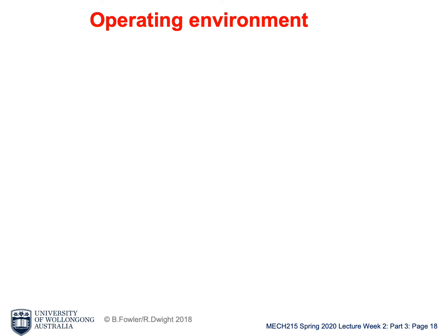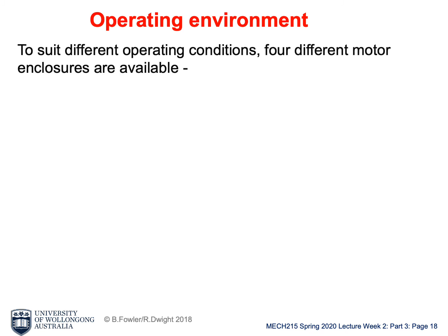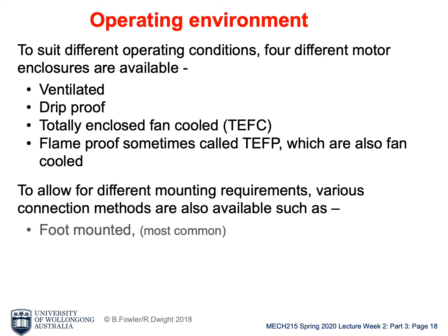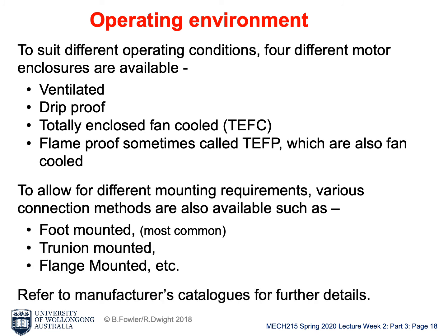In real applications, the operational environment factor is also very, very important. There's a lot of information. If you open any motor catalog, there's a lot of information about how the motor is designed, what the protection rating is, what the cooling setup is, and how the motor is mounted. It can be foot mounted, can be flange mounted, and this information is in the catalog, and we are going to cover it a little bit in the next part.